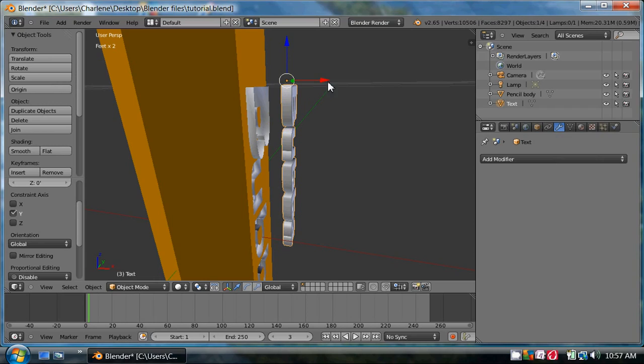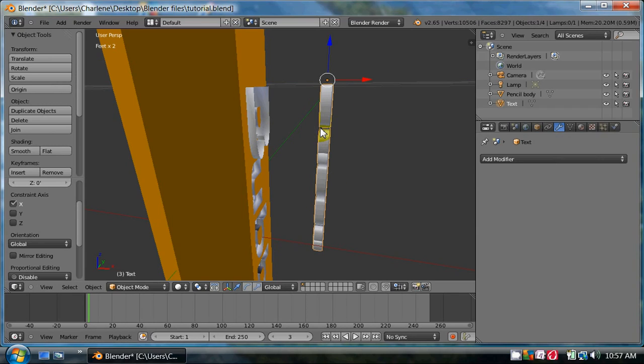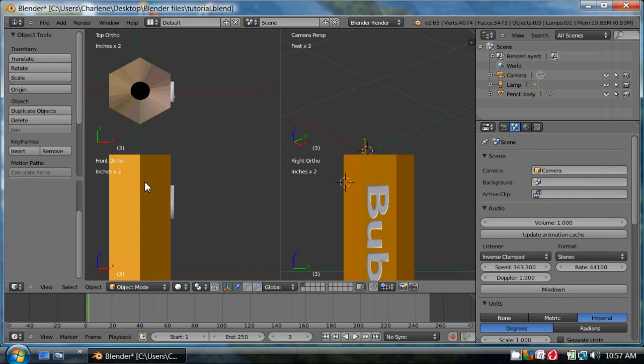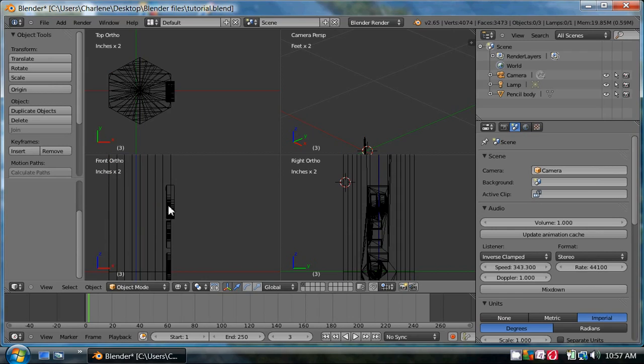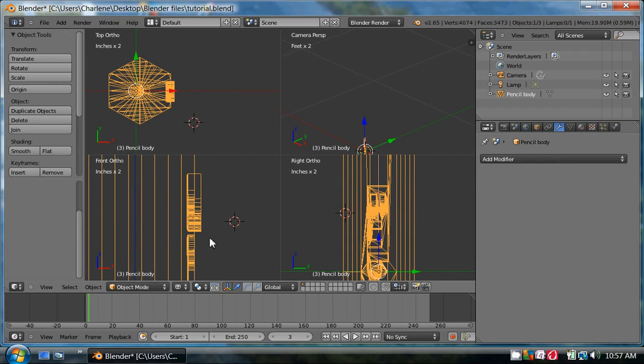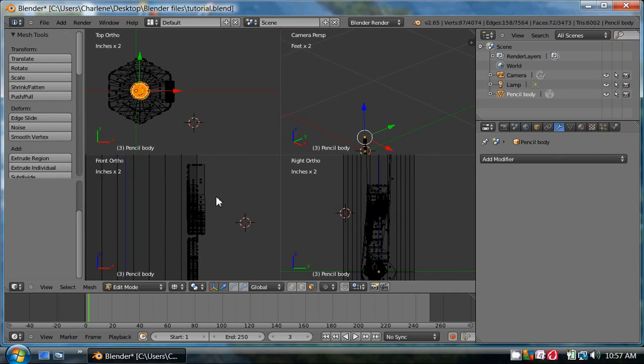So we'll do that. Let's get rid of our tool here, our drilling tool. We'll just hit X, delete, and go back into quad view. We'll put it in wireframe mode here, and let's get our vertices. Actually, yeah, if we select the vertices there, that should take care of the problem. So I'll hit Tab to go into edit mode. Let's see, we're still in object mode here. We need to get into edit mode. Oh, I need to select the object. There we go. Select the object, hit Tab, and that'll put us in edit mode.